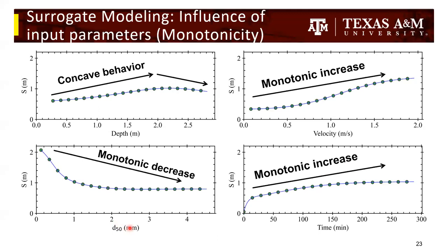As the D50 increases, or the size of the particles increases, the erosion depth gradually decreases. And in general, as the depth of the foundation, or the soil at which the water is interacting, goes down, the erosion increases and then decreases.